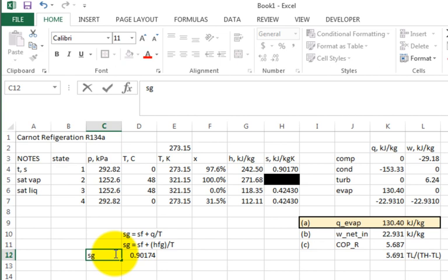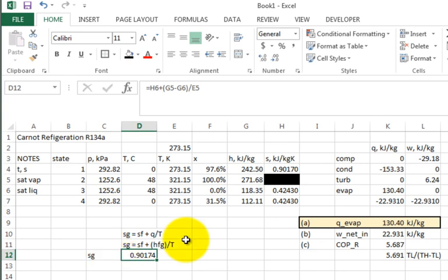See that? Okay. Now we'll go back and compare, because we only were given that number to how many digits in the table? 4. So what did they do? They dropped that last digit, 4. So if you keep all your digits and the table doesn't, then you could get more than 3 significant digits of agreement between the simple equation and the coefficient of performance using the thermodynamic data out of the tables.